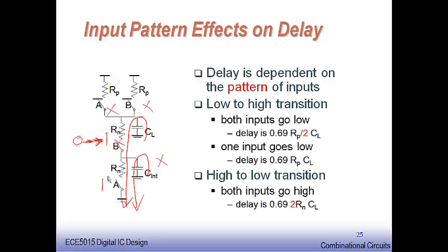Even if there was charge, because this device A happens to be on, when this was 0, whatever charge I had was discharged down to the ground. Therefore, the timing taken by the logic gate to get to 0 from the logic 1 here through these two resistors is going to be comparatively less than in another situation which we will take up now.